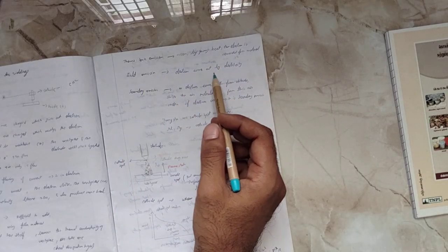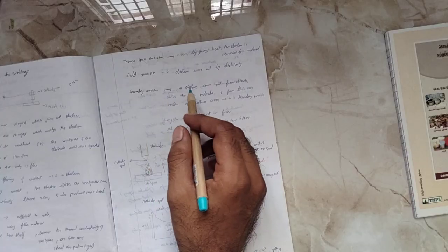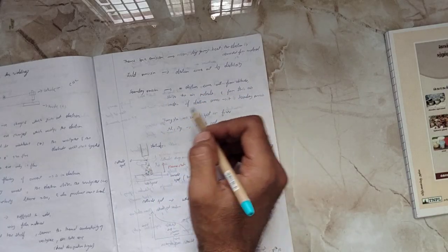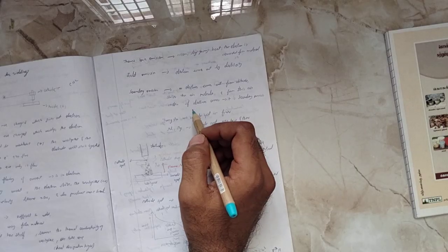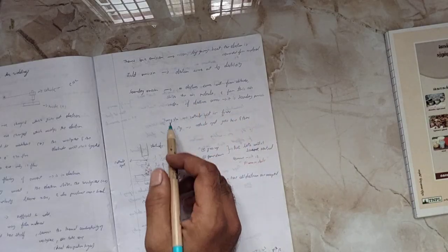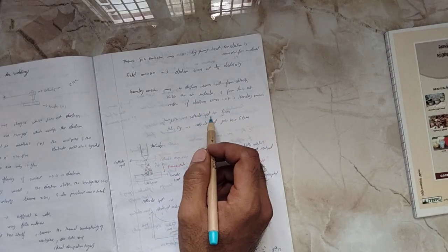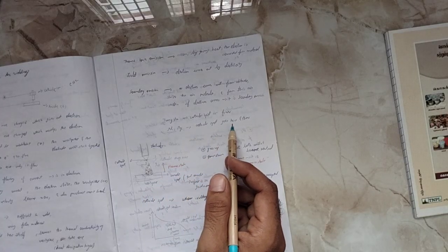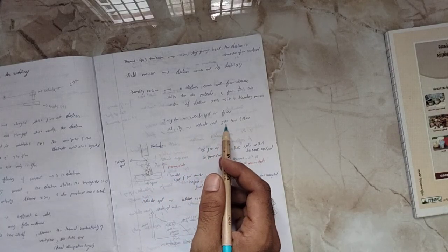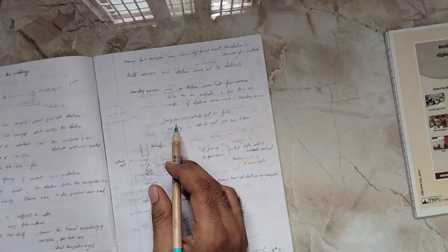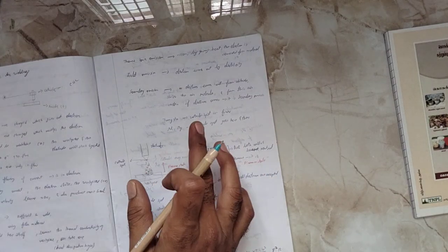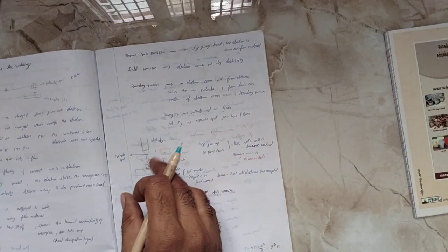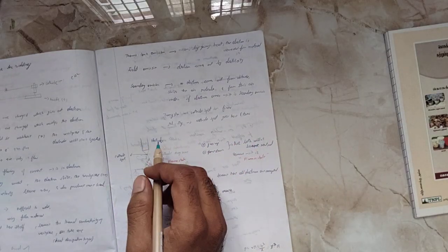You can see electrons come out by the electricity, and in secondary emission you can see an electron comes out from the cathode, strikes an air molecule, and from the air molecule the electron is released. I think you are getting the point. So next one you can see tungsten. With tungsten the cathode spot is fixed, and with aluminum and magnesium the cathode spot moves. Generally guys, if I show you examples, you can have a clear understanding. So we can see how the entire welding process works.